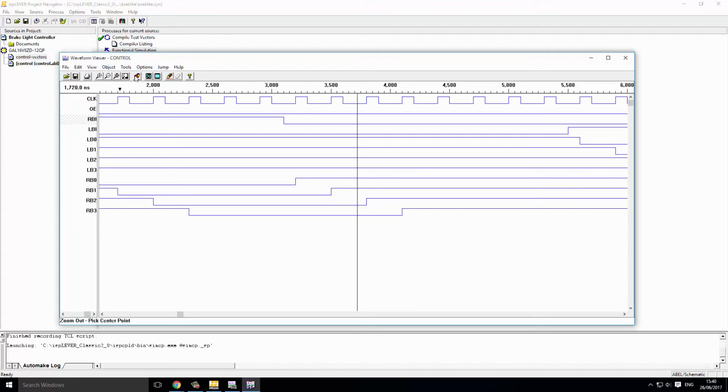Okay, I think we need to do the query to come out of the zoom window, the zoom command. So if you just click on this little head query thing, we've then got the option of querying the waveform again. So we can put our query button down there. We could manually measure that that was at 3,100 nanoseconds and then move the query line to where we start getting output. This time at 3,200, and we can subtract those.